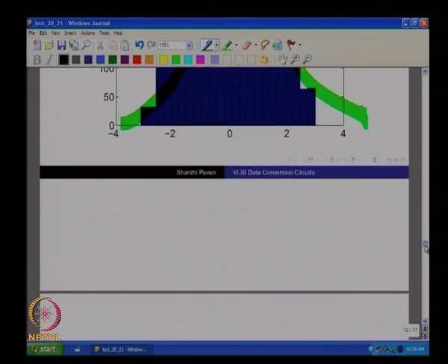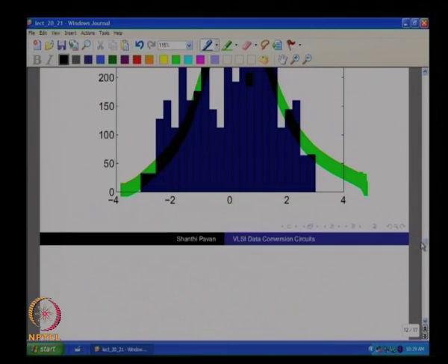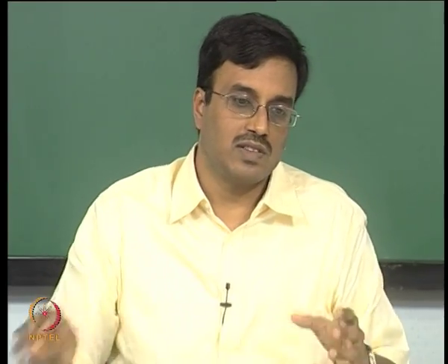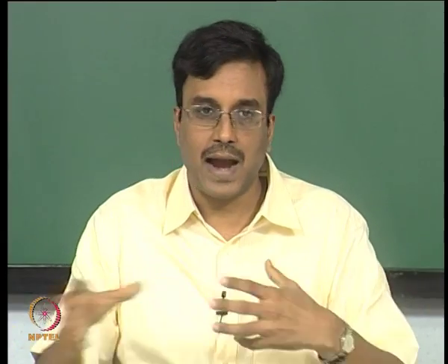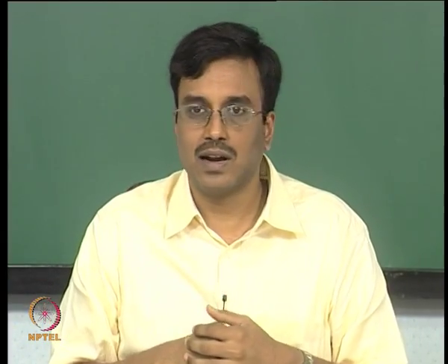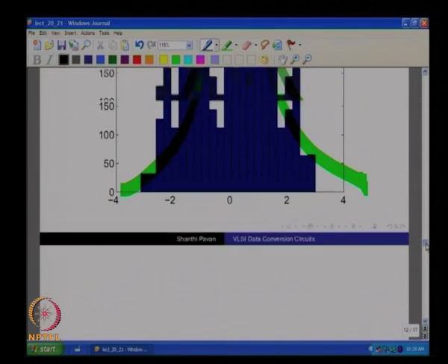So, that is the intuition, at least, for assuming this for the shaped quantization noise. The quantization noise itself is still uniform, but once you pass it through a filter with a reasonably large number of coefficients, you start adding up various uncorrelated random variables and the result starts to look like a random variable whose PDF is Gaussian. Okay. All right.